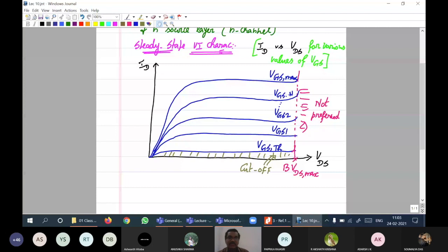Okay. Reason being, there you have current gain. I'm comparing power MOSFET with the power BJT. Power BJT is a current controlled device. Base current is the control terminal. So current gain beta is given by IC by IB. Output current IC divided by control current base, IB. So it was slightly increasing. Therefore, the collector current was not perfectly constant in a power BJT.